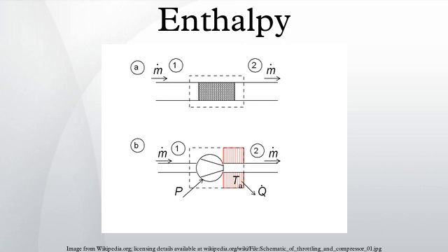Point C in Fig 2 is at 200 bar and room temperature. A Joule-Thomson expansion from 200 bar to 1 bar follows a curve of constant enthalpy of roughly 425 kilojoules per kilogram, a line between the 400 and 450 kilojoules per kilogram isenthalps, and ends in point D, which is at a temperature of about 270 kelvins. Hence the expansion from 200 bar to 1 bar cools nitrogen from 300 K to 270 K. In the valve there is a lot of friction and a lot of entropy is produced, but still the final temperature is below the starting value.